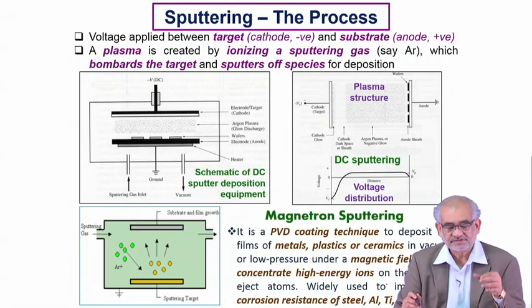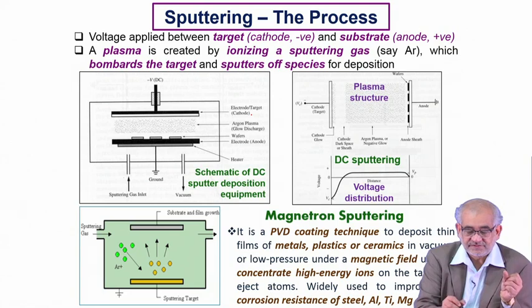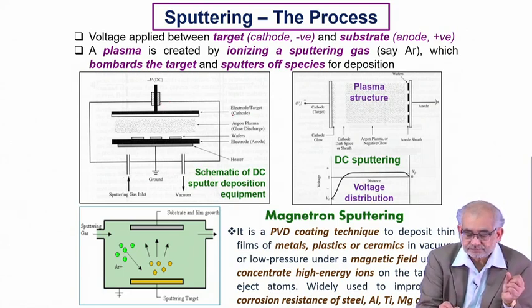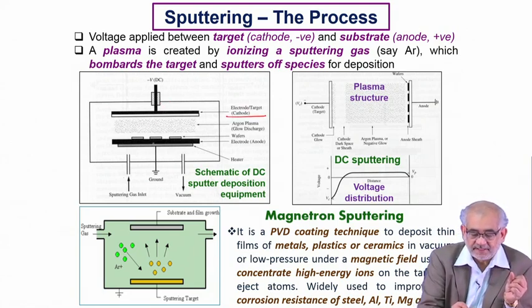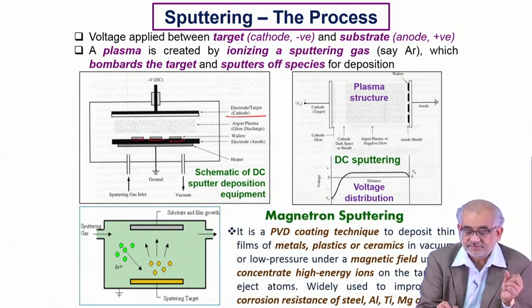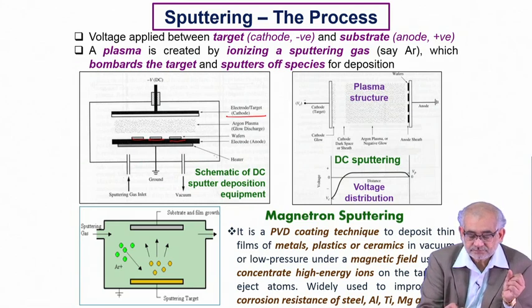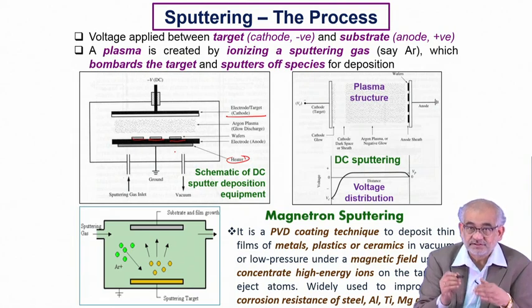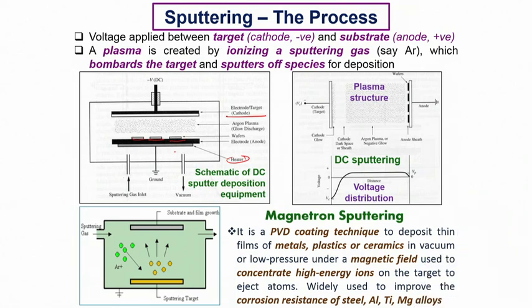Anyway, so the typical process would require that, as I was saying, this is the target and these are the components on which you are depositing, say for example silicon wafers. You may have an auxiliary heater here which allows certain diffusion of the deposit and the substrate below, and in the process the sharp interface can be replaced with a fairly diffuse interface with a better bonding.